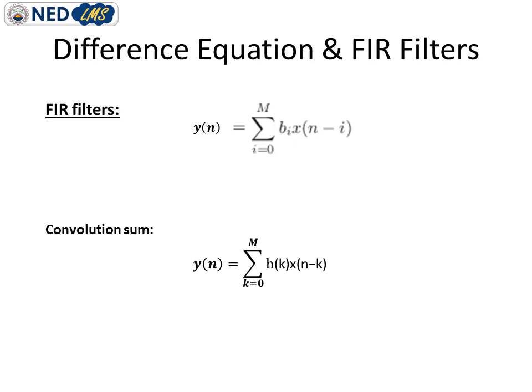For FIR filters, we already know that the recursive part equals 0. So the equation remains with only the non-recursive part, which is the delayed version of input, x of n minus i, or we can say x of n minus k if we assume the delay variable as k. So for an FIR filter, the recursive part is 0 and the equation becomes like this, as displayed in the slide.